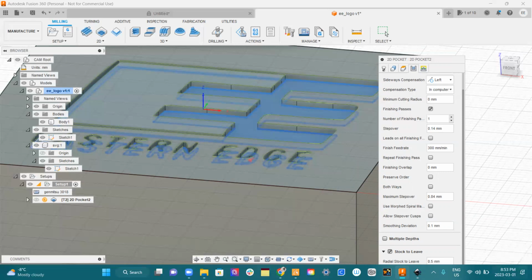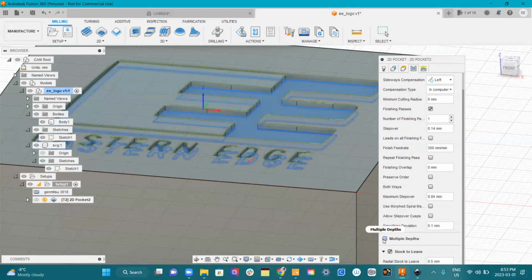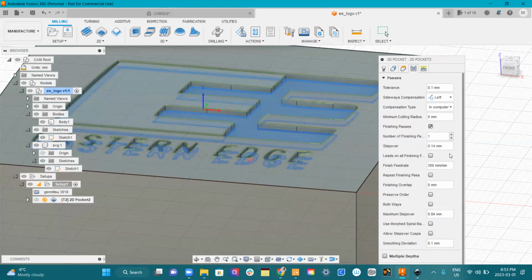But it's, I don't know. So you wouldn't put the bottom as, say, I want it to be 10 millimeters deep? Would the bottom be 10? Yeah, you set the bottom to 10, and then right here when I'm setting these configurations, it's how much it moves down until it gets to the 10. So it's going to determine that it's doing a certain number of cuts before it gets down.